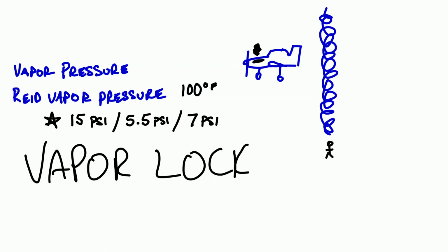Now, you may have wondered why I just said in flight. Well, here's where this whole column of air thing comes in. As the aircraft gets higher and higher, so as we travel up higher into this column of air, we have less and less weight pressing down. We see that as lower atmospheric pressure and lower density. The density will come in here in a minute, but that lower pressure is important. Once we start getting lower and lower pressures, combined with high temperatures underneath the cowling, then we can end up in a situation where the fuel would want to vaporize and create a vapor lock.